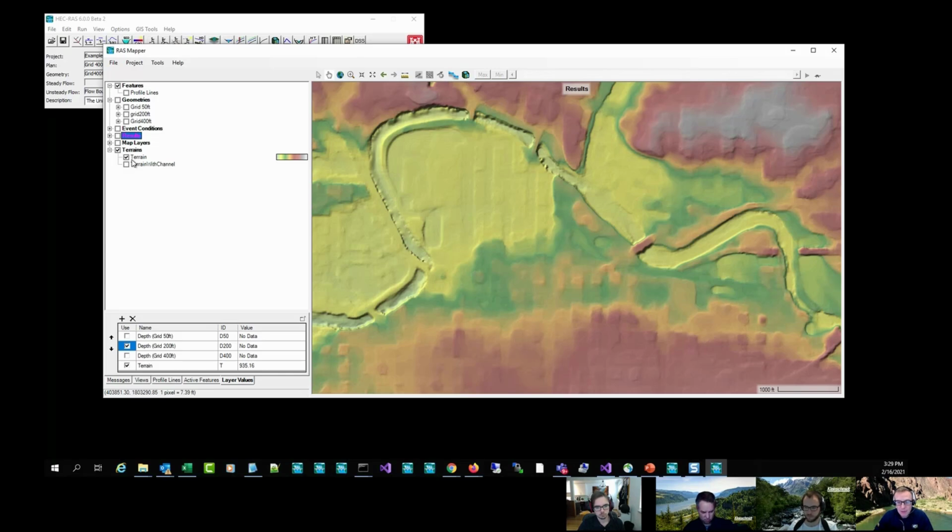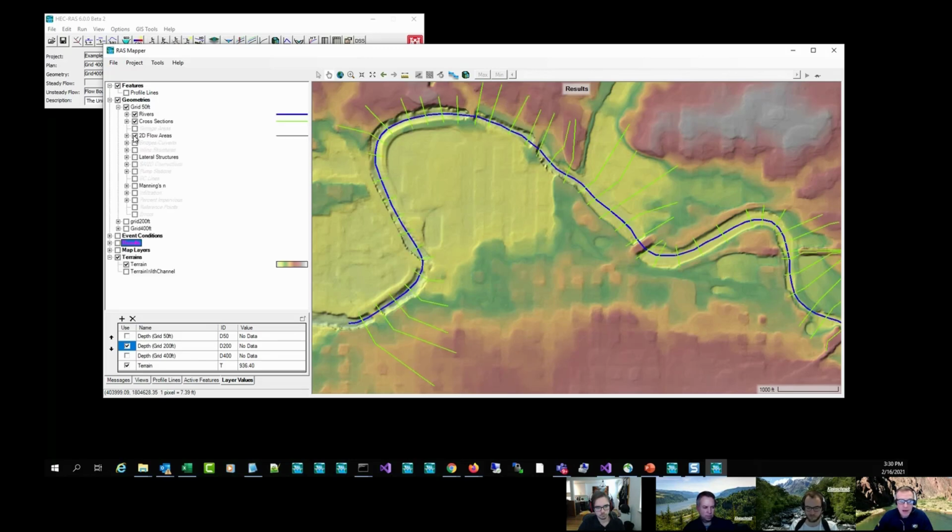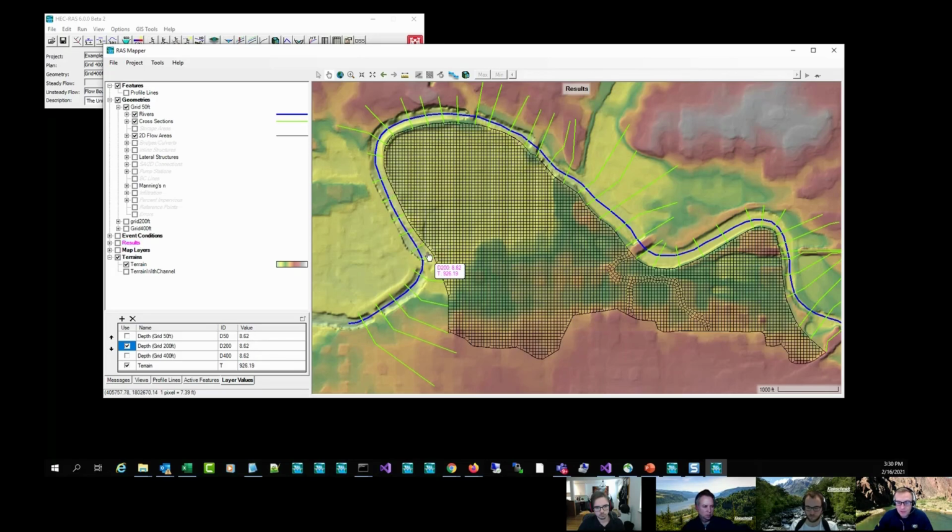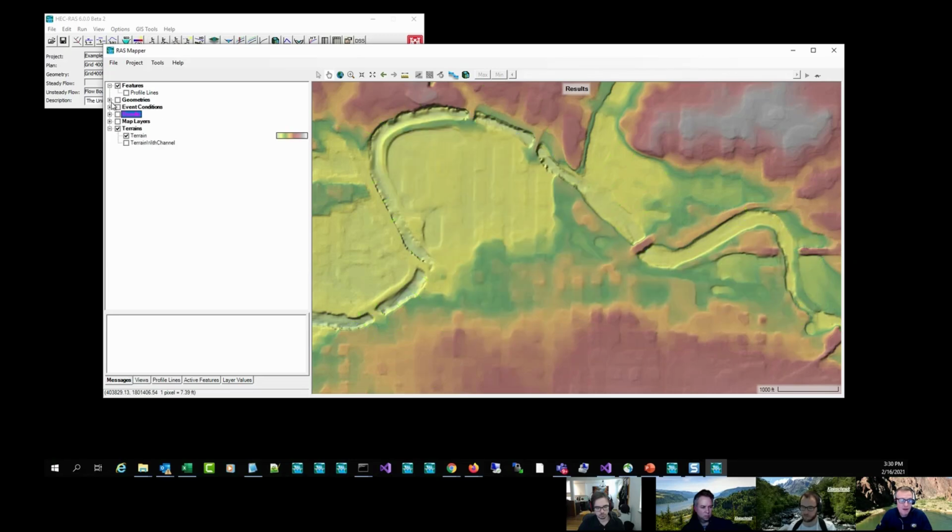It really became a problem when we had these combined models. So we look at this model here. We've got this combined model where we have a levee system that's running between the 1D model and the 2D model. And you start to realize that no matter how good your terrain model is, you're never going to represent that levee with the coarse resolution of the grid. But the grid's fine for everywhere else, just not for these linear features. So we really needed a vector addition. So we've gone to the idea of the raster data being the underlying body of work, but that we can then modify the terrain layer with vector additions to have more precise data handling.